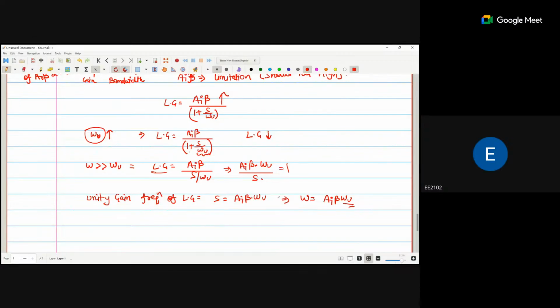Any other topic? We calculate the Bode plot to find the exact stability criteria: what value we should consider for omega u so that the system Bode plot provides me a stable system. For that particular purpose we are calculating the Bode plot.